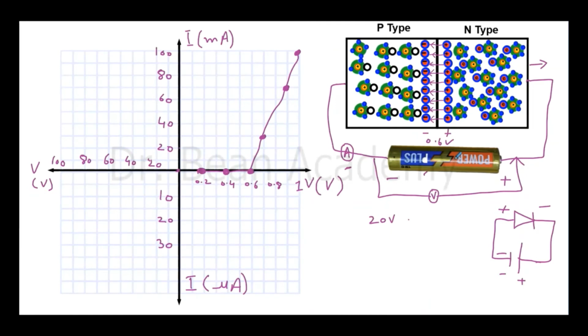We are doing the opposite of forward bias mode, because now we are bringing these electrons away from the barrier, and it seems like the barrier is actually increasing in width. And the same is the case on the negative side. These electrons will flow to fill the holes, so the number of holes will decrease. So you can see that we are actually increasing the width of this potential barrier at the middle.